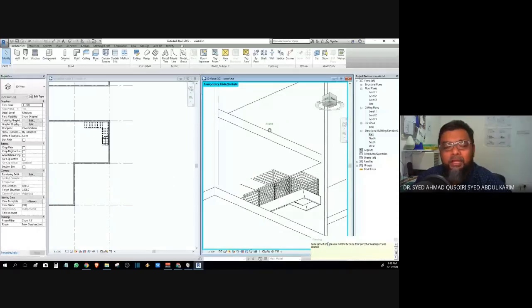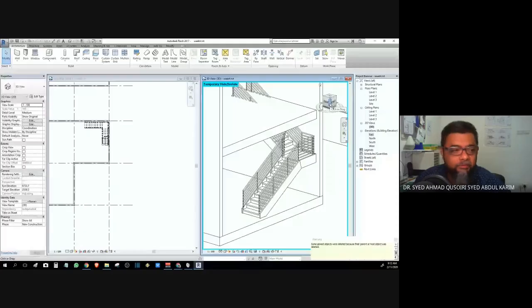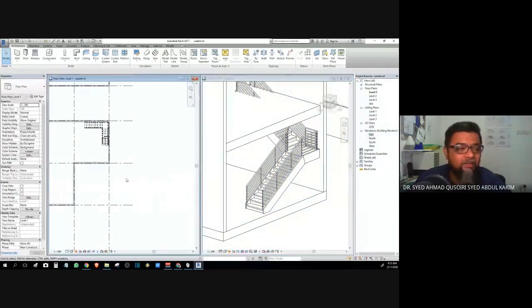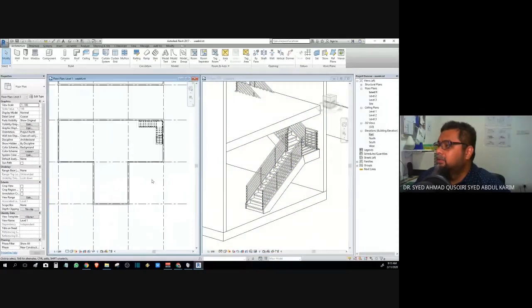So we need to create an opening at the suspended floor as the stairwell, so called, for the access for the stairs. Okay. So to do that, since we are editing the suspended floor, we want to be at the second level.